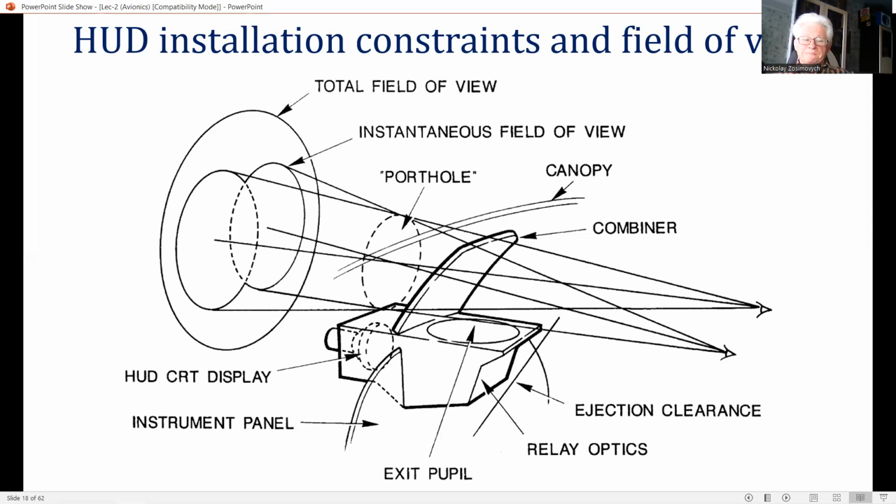These parameters are usually balanced against the need for a large diameter collimating lens to give the maximum IFOV and a large focal length, which allows maximum accuracy. The diameter of the collimating lens is generally limited to between 75 millimeters and 175 millimeters, or 3 inches and 7 inches approximately.